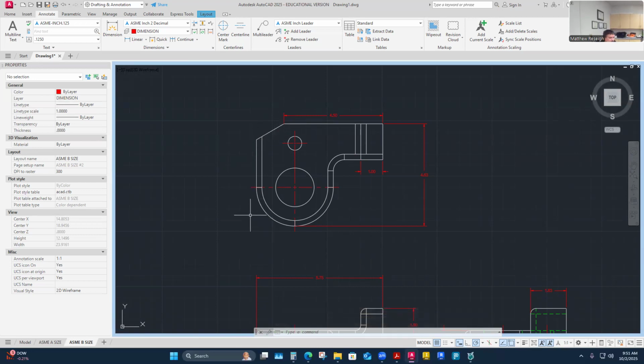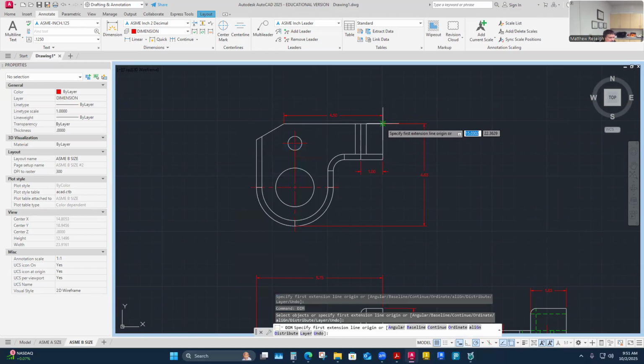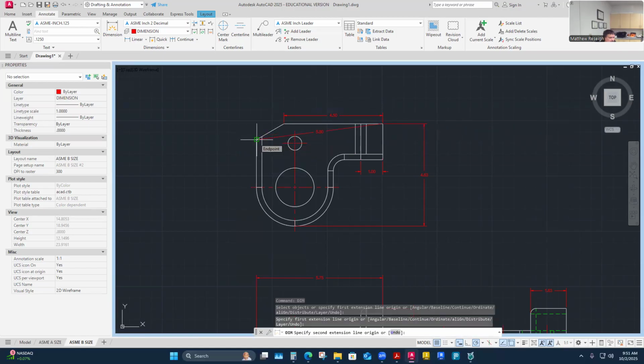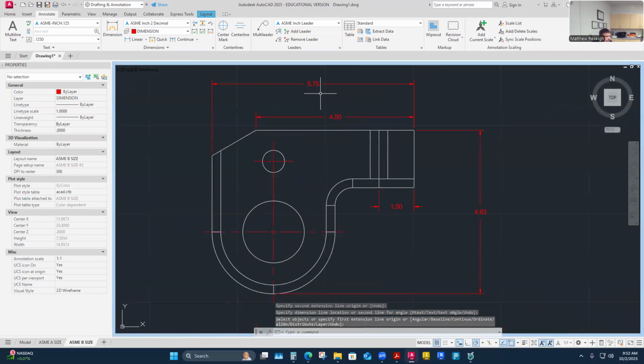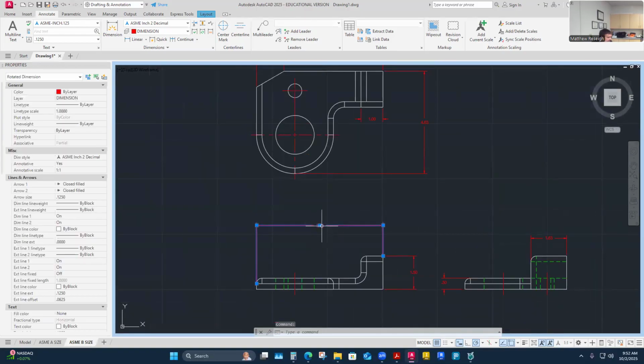So I think I will probably move that up, because I'm thinking about it as helping to define in the X direction, pulling from this point over to there. So I feel like this is probably a better choice for that overall dimension, to bundle and save. These are both points associated with this miter. Plus it doubles as an overall dimension, and maybe I can eliminate this one.